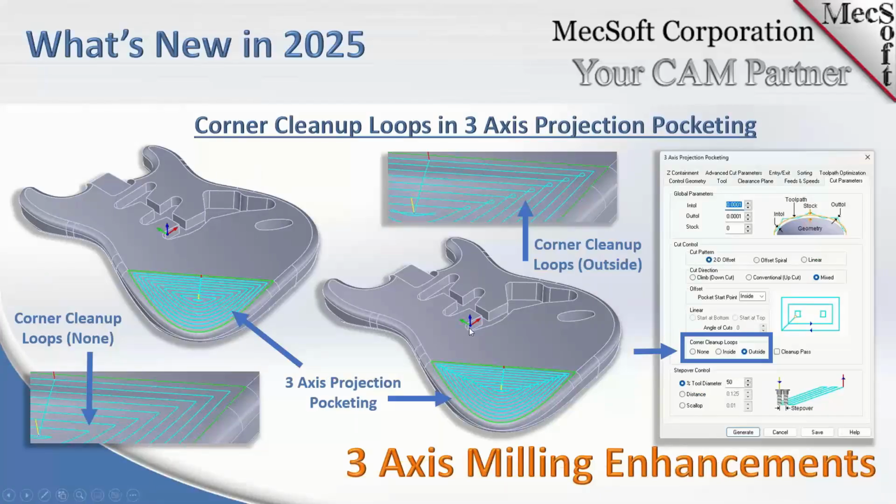Okay, here's a good one too in 3-axis. We've added corner cleanup loops. If you're unfamiliar with corner cleanup, let's just look at the pictures here. Corner cleanup is actually in 2-axis, and now we're adding it in some 3-axis operation types. I believe it's also already available in the cutting in levels in 3-axis, such as clearing flats on horizontal roughing, etc. But now we've actually added it to a toolpath that is not planar.